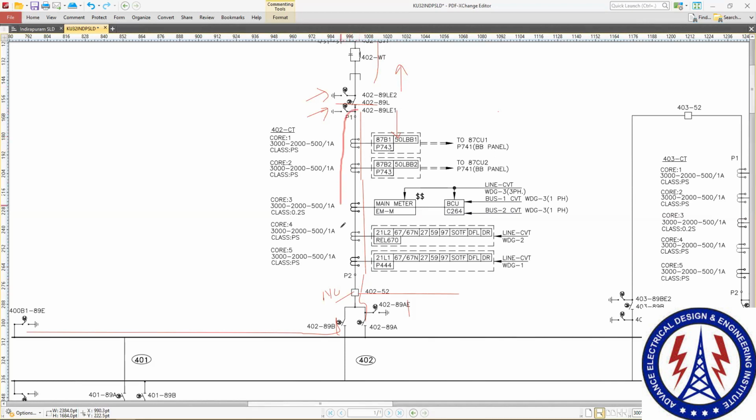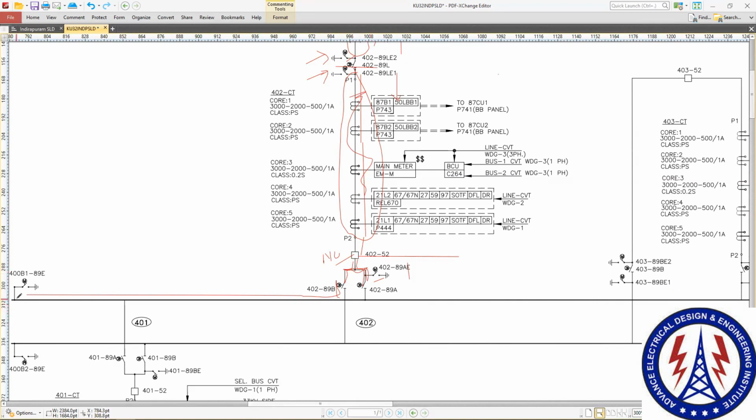So this part is standalone, and then this above part and this downside part. So that is why four earth switches are required. One earth switch, a second earth switch for this region, a third earth switch for this complete region if you see, and the other earth switch is for this particular region, and another earth switch will be connected here. So this is the reason why we are giving these earth switches.